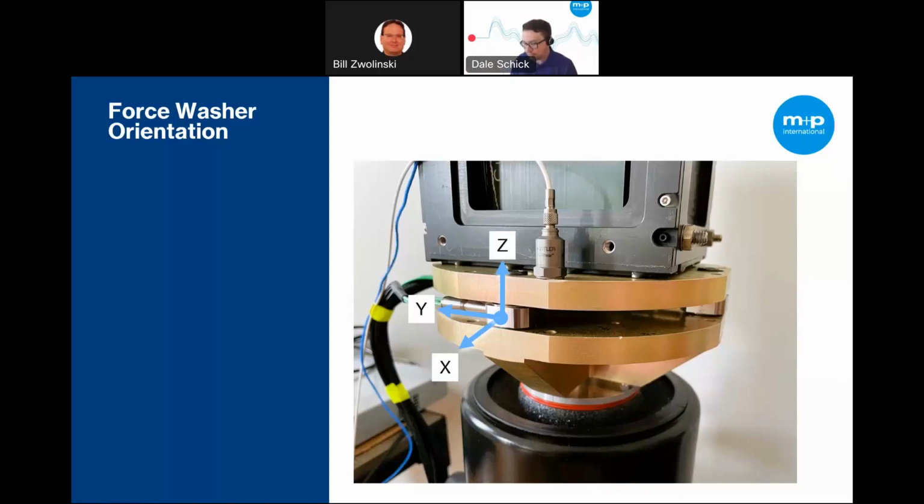So if I had used the engineered bolt with the ring nut, the engineered bolt would actually bolt into the expander head here on the bottom, and then it would protrude through the top. And at that point, you could set the force sensor on top, load the force ring, and all you would need to do is make sure that the force sensors aren't off axis, which, as you saw before, some customers use some clever fixtures in order to keep those in place. But all this is to say that I think the engineered bolt and the ring nut are probably one of the easier ways to install a system.